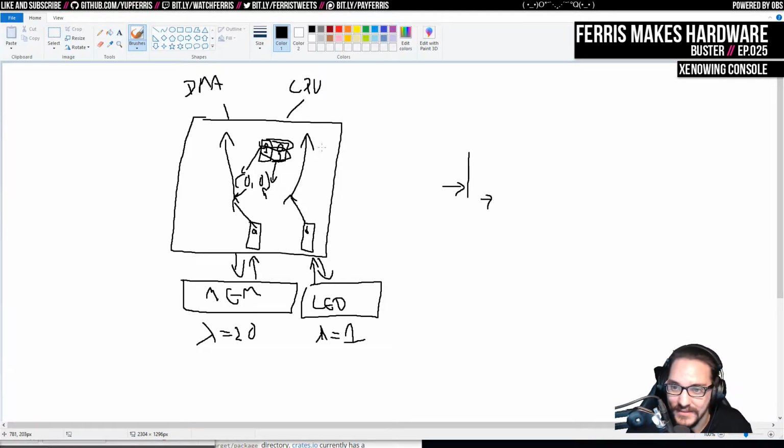So the kind of downside of this is that it serializes all the results of the reads. So if one read is issued really early on that has really high latency, all of these other reads are going to be behind that. But if you make these FIFOs fairly deep, then at least you can issue a bunch more reads in maybe some common cases. So at the very least, the throughput should still be pretty good, even though the latency in some cases is going to be pretty bad. It's going to be dominated by whatever slave has the most latency. But again, I think better systems like this could be designed, but I think this is what I'm going for because it should be relatively simple to implement.